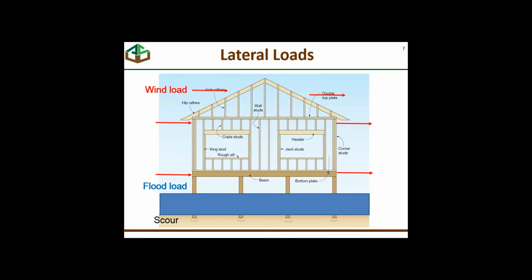And then where we have flood, we typically have scour. So I hope you saw the little scour thing pop up at the bottom. Scour to us in this presentation and talking about foundation design is important because scour is the washing away of supporting soil around the foundation element. If it's a pile or a column, typically that scour occurs conically and will reduce the amount of lateral support that soil provides around that foundation element.